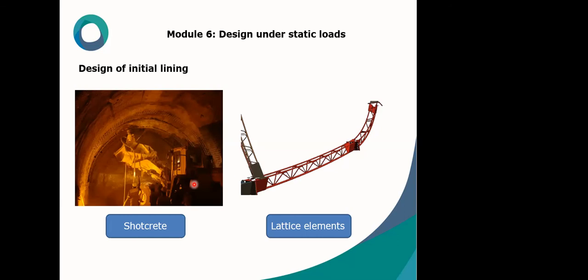The workability or efficiency duration for initial lining is less than 2 years. So the seismic loads aren't considered in designing initial linings. On the other hand, there is an obligation to construct the final lining in its section of the tunnel within 2 years from the completion of the initial lining construction.